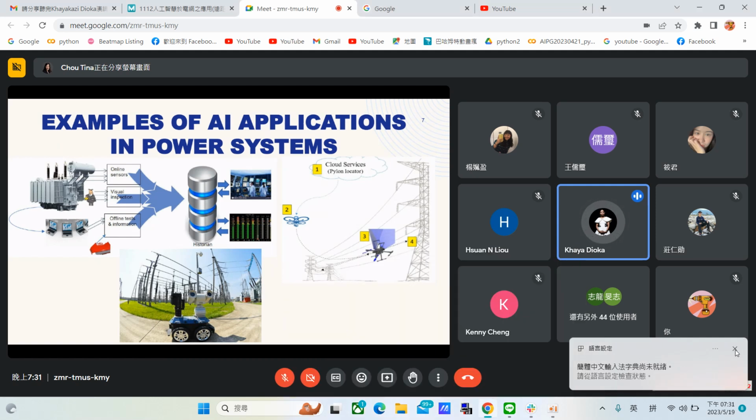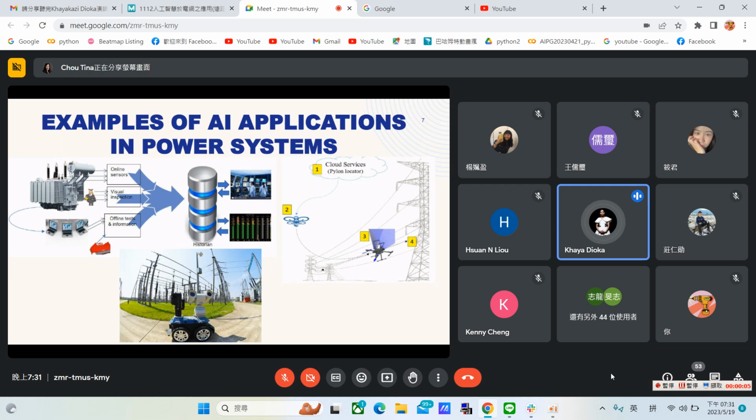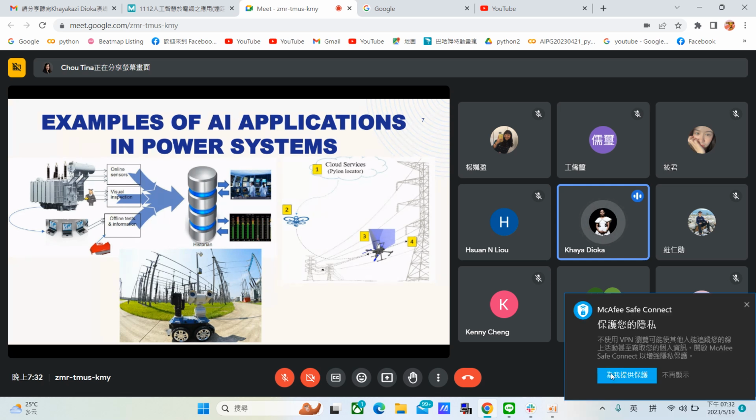Robot in a substation that does the visual inspection. You also have all your offline tests and information. So you have all that information coming together into a computer system using algorithms to indicate the state of that transformer. So you've got your asset, and then you've got your computer system and algorithm to indicate the state of your transformer, and also for the operator to make a decision whether the transformer must be switched off or not, should you be having severe alarms coming from that transformer.